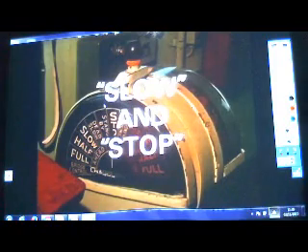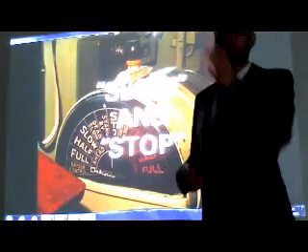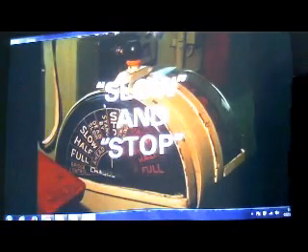Always another handy tip to bear in mind is keep the 50% always for emergency use. Do not always use all full 100% of your vessel's maneuvering capability when you are maneuvering in close quarters. Keep always 50% if you need it to go the other way. Control, slow and steady. Okay?